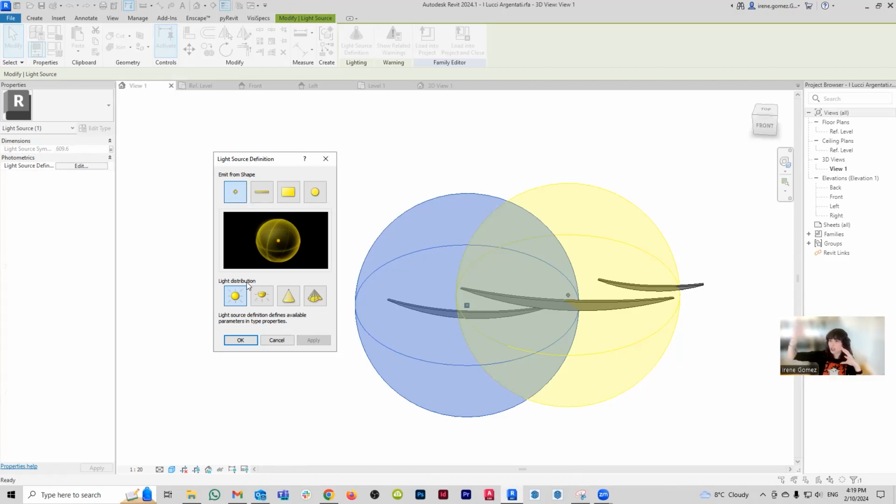The distribution is in which direction the glow goes. A spherical means that it goes in all directions, similar to what you would see with a traditional incandescent bulb. Hemisphere is a little bit better for the intents and purposes of this exercise because it's cut in half. This one is really good when you have light sources that are right next to a surface. So think about a floor light, a wall light, a ceiling light. Still not perfect. We have spotlight. Spotlight is going to basically generate a cone of light. This one could be better, but my favorites are photometric maps, also known as IES.